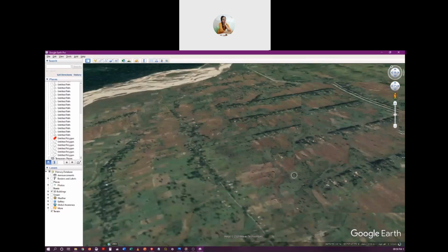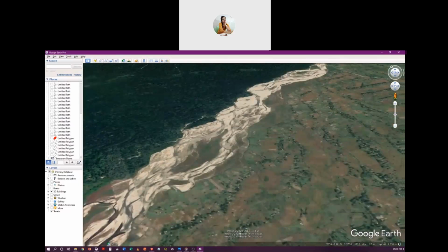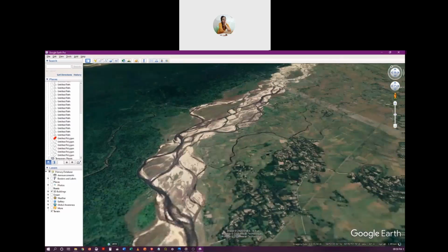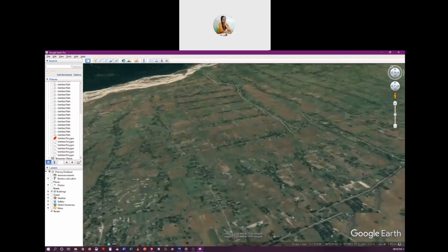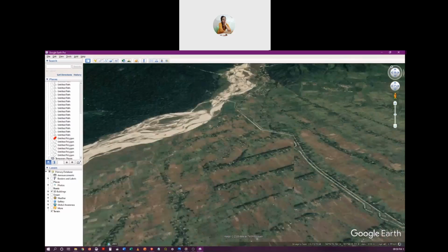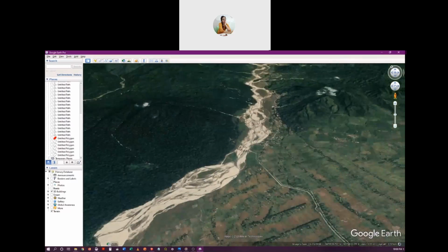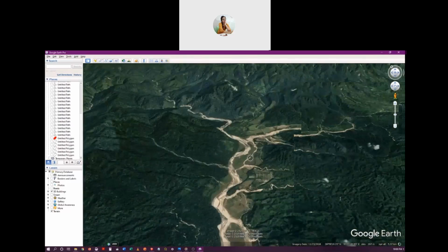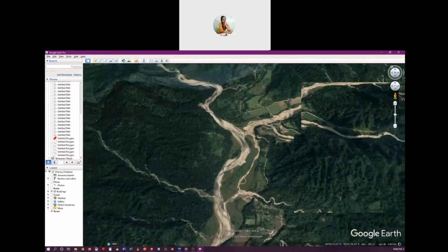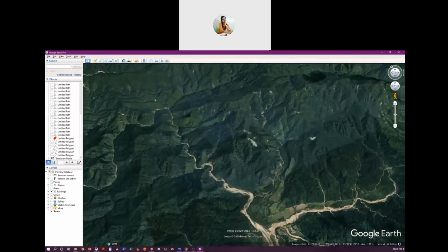And if we construct the divergent headwork much lower than that, suppose somewhere around here, then we would lose the ability to command the portion in the higher elevations, that is here. We can command a greater amount of area by constructing this project even higher up in the river, but that will cause some other problems.